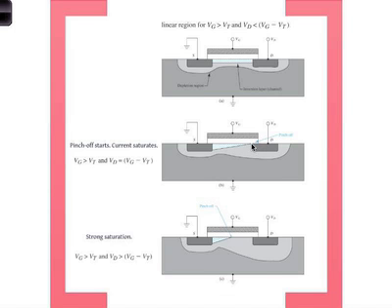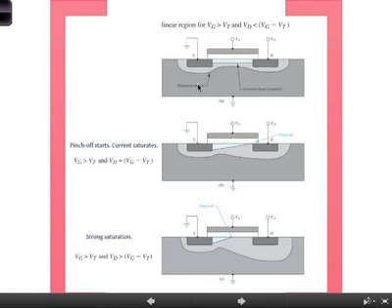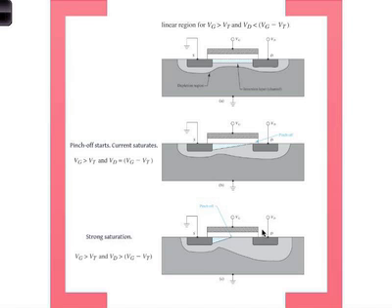So we have a linear regime, which is over here, which basically acts as a resistor, and then we have the saturation regime. This is just at saturation, this is beyond saturation. Okay. And the principle is the same as the FET. So make sure you keep this qualitative picture in mind as you muddle through the math, because otherwise it won't make much sense. Okay, so next,